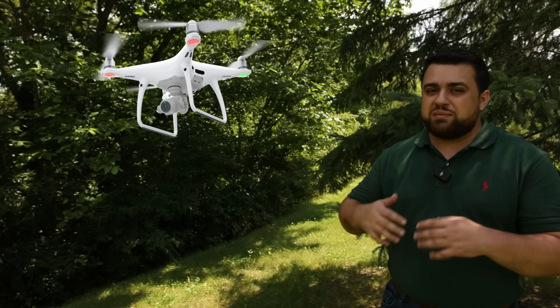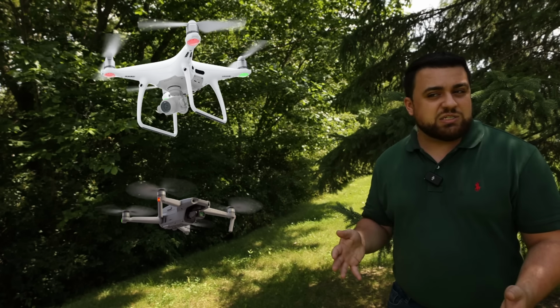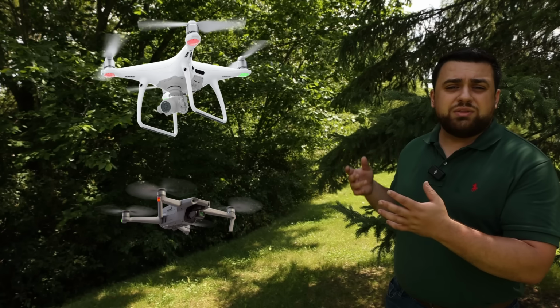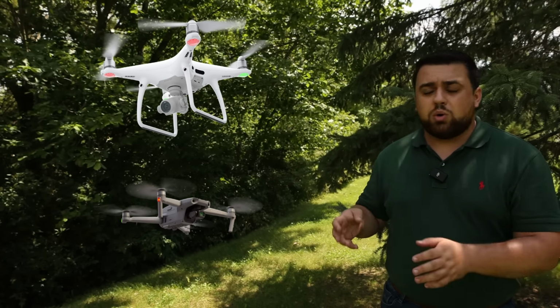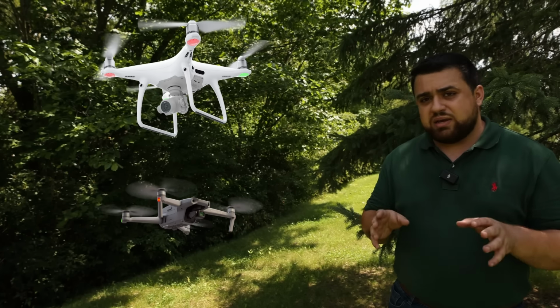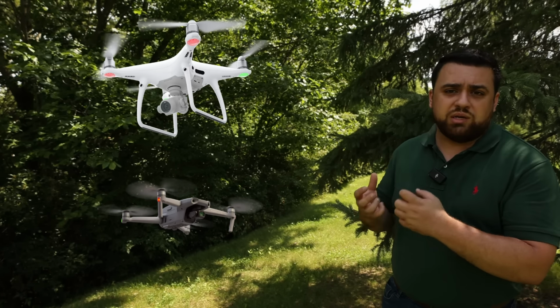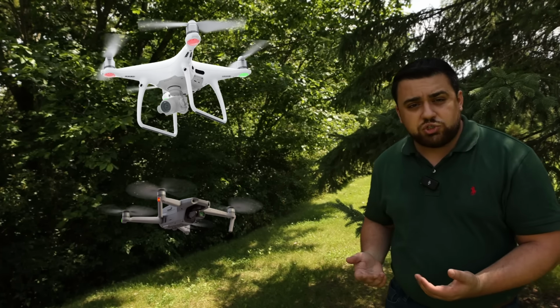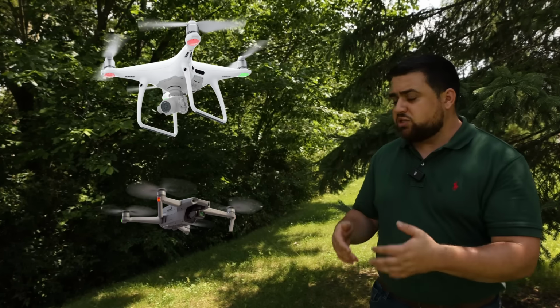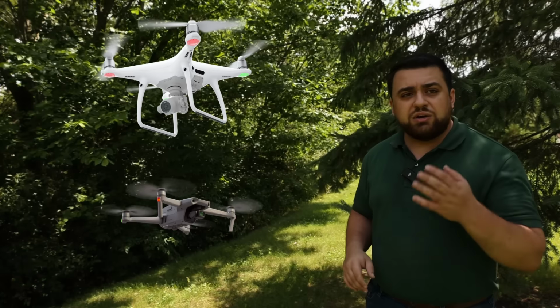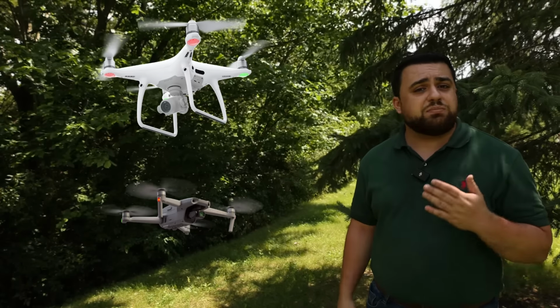Now, there are many drones that can be used for surveying. If you're just starting out and you're looking for a budget-friendly drone, then I would recommend the Phantom 4 or the Mavic 2. These drones are fairly inexpensive and you can buy them on Amazon. Now, while these drones do have a decent camera, they do have a linear rolling shutter or an electronic shutter. I'll explain in a minute what that is, but this does affect the quality of the imagery. Now, this doesn't mean you can't use these drones. You'll just have to fly a little bit slower and only fly smaller sites. For someone that's just starting out and doesn't have a lot of money, if you've gotten your 107, this could be a decent option to get started.